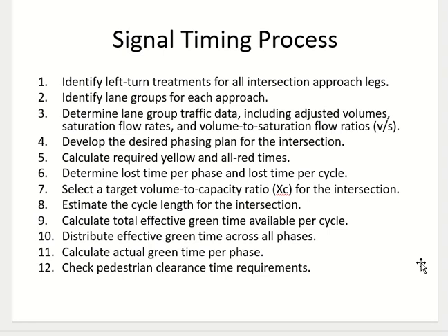There is effective green and there is all red. When there are no vehicles in the intersection. The time when it is green with nobody moving, when no vehicles are entering the intersection, because of preparation or because of all red, whatever. So this is the lost time.